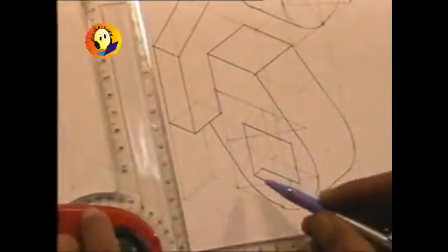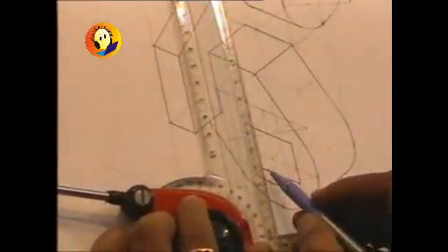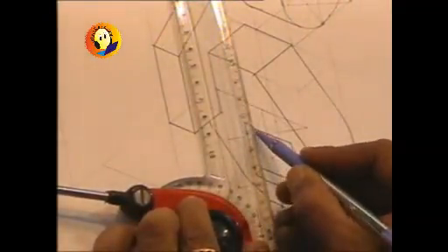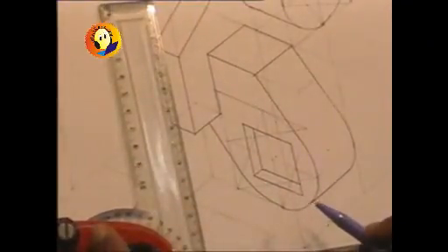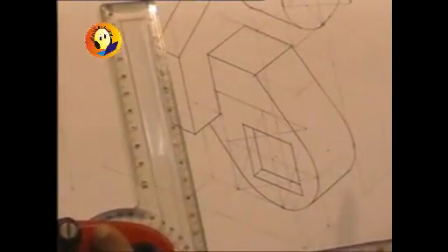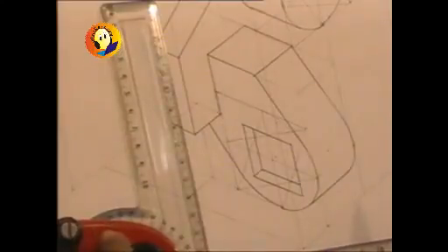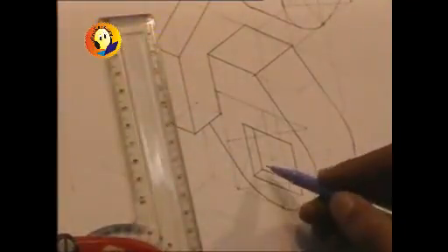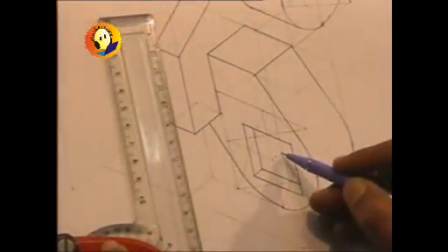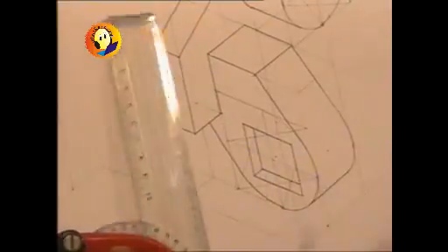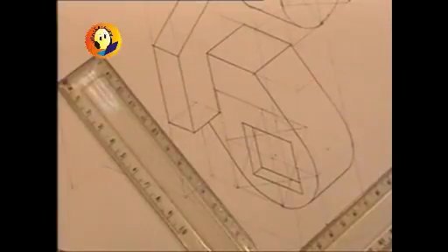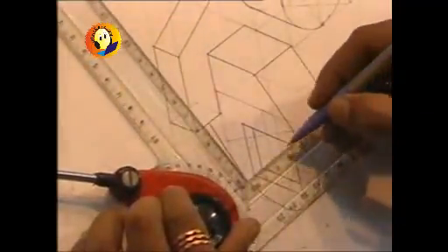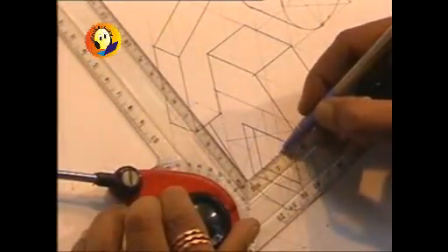So once we take the thickness of 6 millimeters, then we can show the inside part of that square, and we are required to show one more square hole which is of 15. Now to show that, either we will shift this center inside by 6 millimeters, and then we should be drawing the portion of the square which is visible. Technique remains the same. Shift the center by 6 millimeters first.